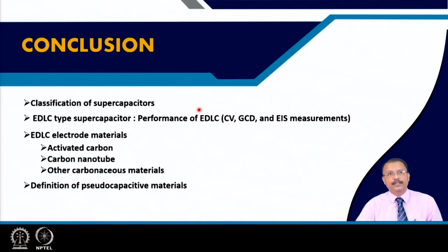So, in this particular lecture we talked about the classification of the supercapacitor. We made it only EDLC type and the pseudocapacitor type, but we can also expand this kind of classification, and mostly we concentrated the discussion on EDLC type supercapacitor and how you can estimate the performance of an EDLC from cyclic voltammetry, then galvanostatic charge discharge or electrochemical impedance spectroscopy measurement, what information you get.